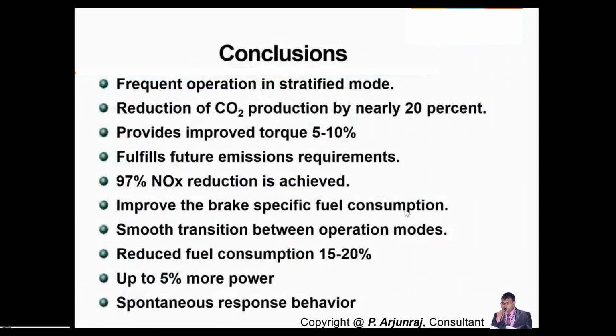This will also improve the brake fuel consumption. It will improve in the sense it's not going to increase. Basically the BSFC of the engine is going to be lesser. It means the fuel consumption is going to be lesser, which means the mileage is going to be higher. You have to take improve in that manner. It's not that it's going to increase and reduce the mileage; that is not going to happen in the case of GDI. When I say improve, it is better with respect to fuel consumption. The fuel consumption is lesser, which means the mileage is better.